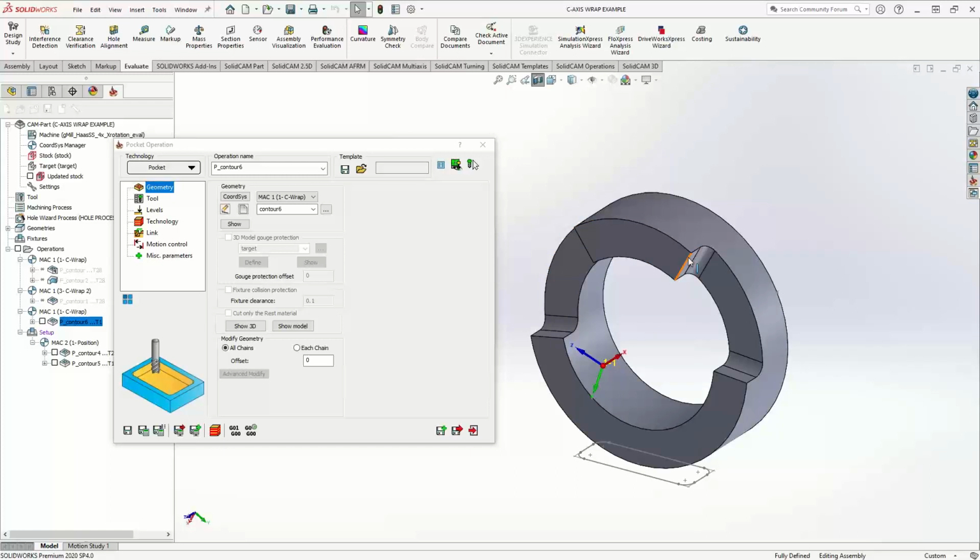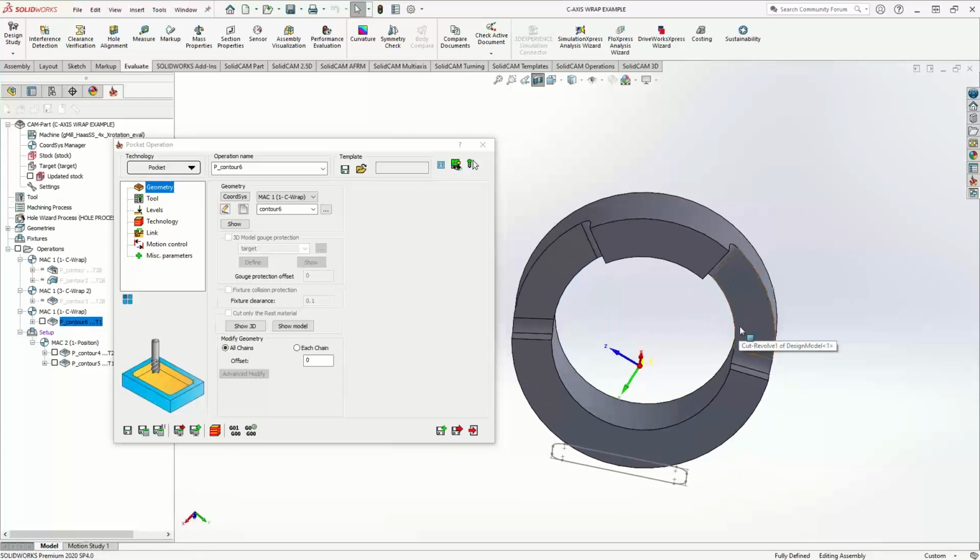So if you just do a point-to-point from one point to another, even though it's a straight line, all of that gets projected to the tool plane. In the case of wrapping, it will be projected to the tool plane, but in a wrap. I think I've been able to get away with it before. It's probably not entirely accurate for the pocket, but it is something you can do to close the gap. But in this case, I'm just using the cross-section view so we can actually see down the pocket when we talk about the depths.